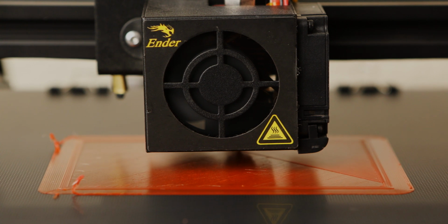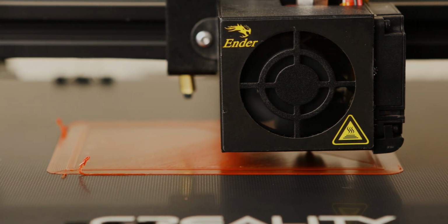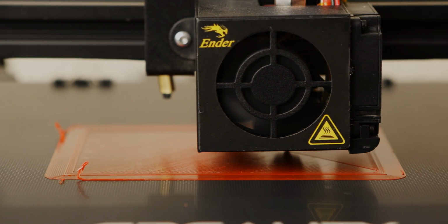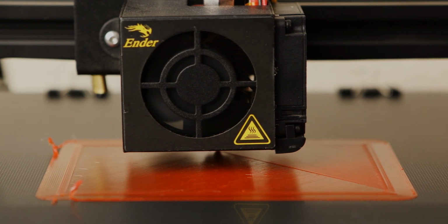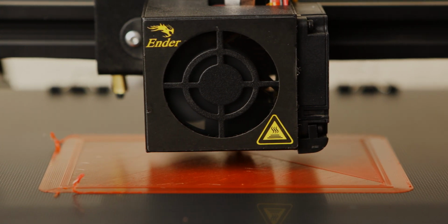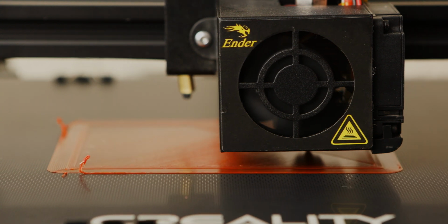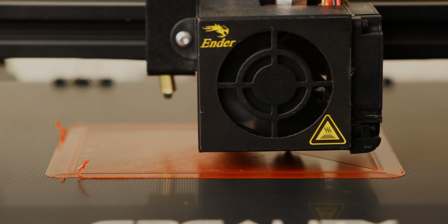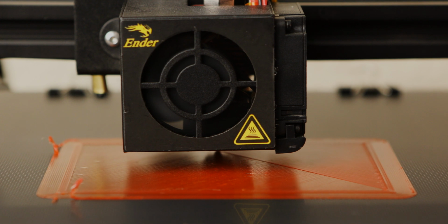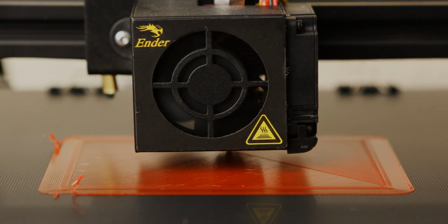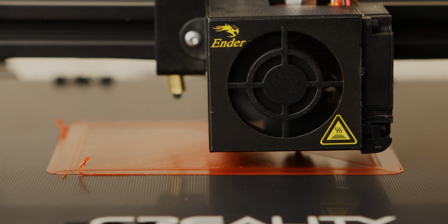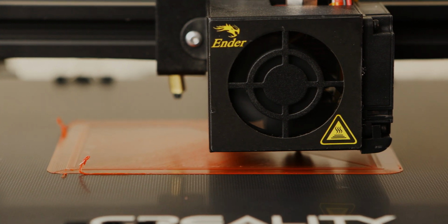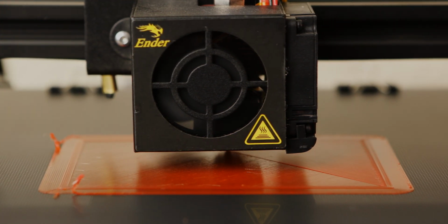printer. At that point, I mean, the plastic was probably not ideal, and I also had to do an adjustment on the Z height and baby step it so that the bed went 2 clicks higher to the nozzle, or the Z lead screw actually is the one that moved, obviously. Some printers have the bed move, but for this one it's the actual whole assembly that carries the nozzle. So there's no issues going on with extrusion, and at this point I'm fairly confident that the rest of the print will go on and be successful. So I'm going to go ahead and set up a time lapse and let you guys see the progress.